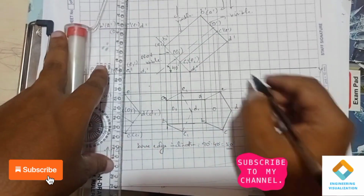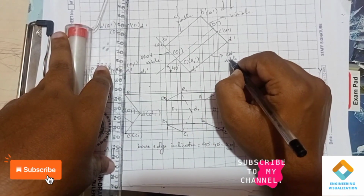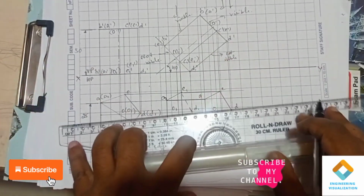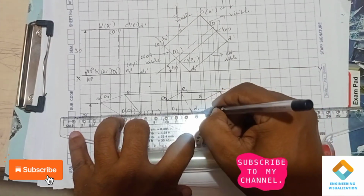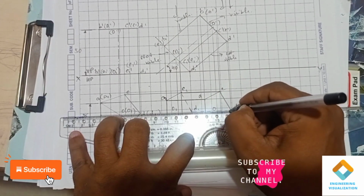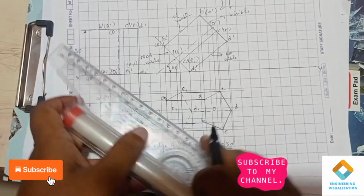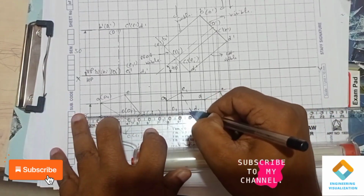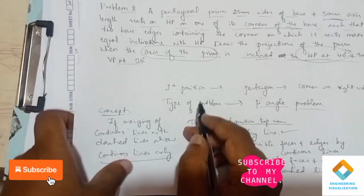Now this edge is also not visible from the top view, that is D dash and D1 dash. As we write in the top view, it will be from D1 to D. That will be the dashed line here. Now you can see here we need to write finally the axis, from O1 to O, but part of the axis I can show because there is already a dashed line there. Now the third position.